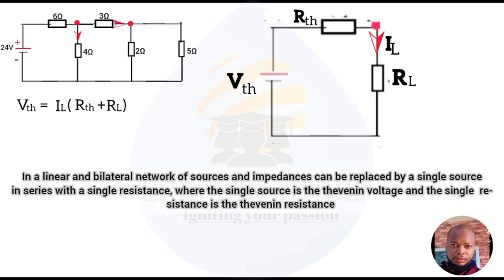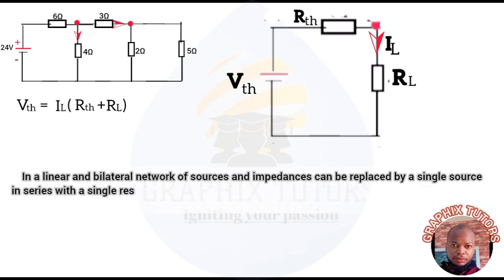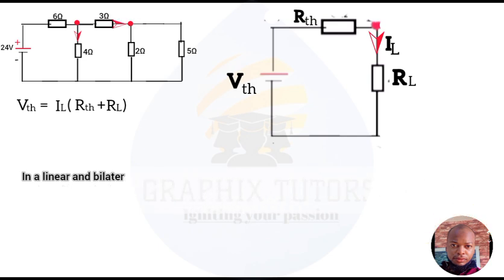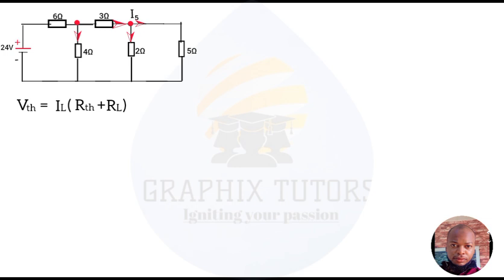So this is what the entire statement is making us understand, and it's still linked to Ohm's law, because in Ohm's law we say V is equal to I R, and the V here is what you can see as Thevenin voltage. The I here is the I sub L flowing through the investigating resistor, and the R equivalent is the two resistances, which is the Thevenin resistance and the R load, which are in series. That's what we have here. So I'll term it my equation 1.